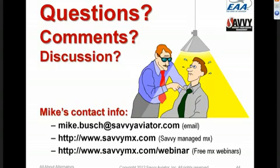Jim has a question a couple of people have asked, which is, if my plane has a single alternator, is there any way to add a backup alternator, or does it even make any sort of sense? Absolutely, there's a way to add a backup alternator, and it probably does make a lot of sense. There are really two solutions I can think of. BNC Specialty Products in Newton, Kansas makes backup alternators that are designed to mount on the accessory pad, the same pad that you'd mount a vacuum pump on.